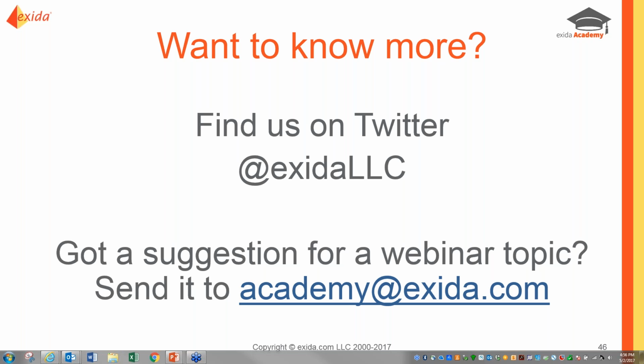Proof testing should also link to the PFD calculations. I'm not sure what we mean, I'm not familiar with that acronym FDT. But if you're talking failure rate calculations, absolutely. Proof test coverage is part of those calculations. That's why we need to know what our proof testing capability will be early on in order to determine what proof test coverage is.